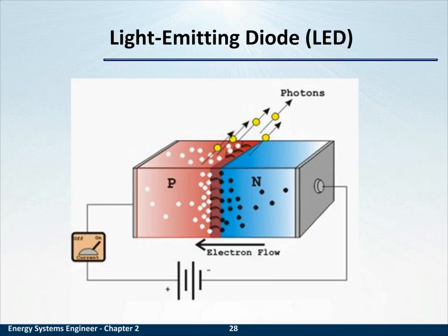But that's another time. Although LEDs you see here don't have a filament that heats up and wastes energy like an incandescent lamp, the whole LED efficiency is largely tied to ambient temperature. Therefore, when you see LED solutions, you'll see them as fixture and lamp combinations designed together, because the integrated heat sink, that part of the fixture that gets rid of the excess heat to keep the LED efficient, must be designed for that LED fixture.